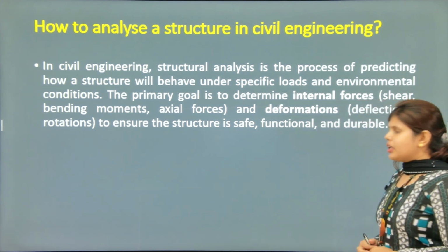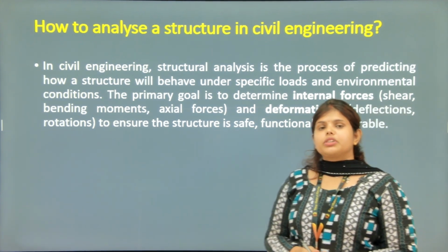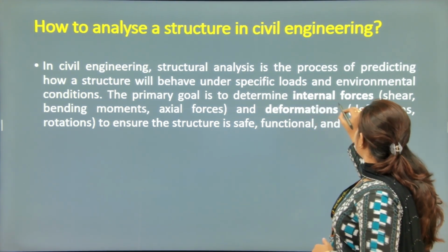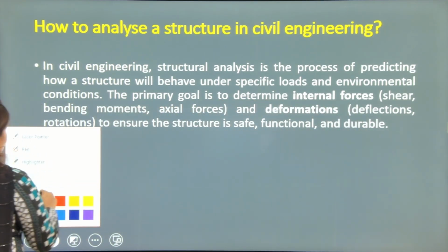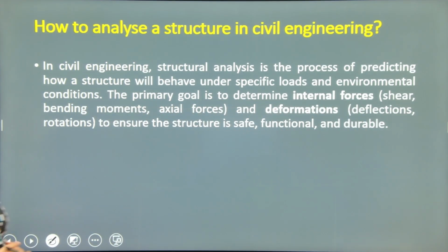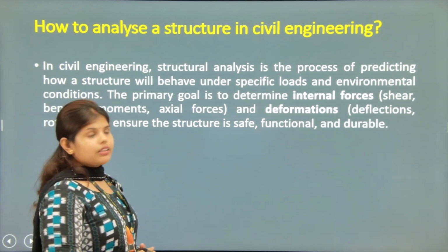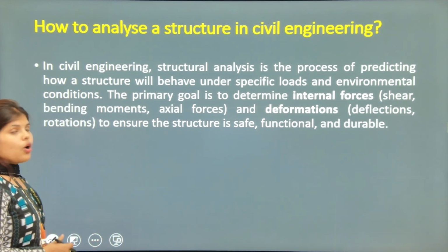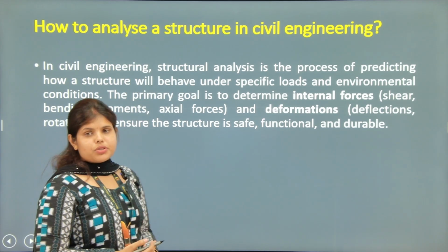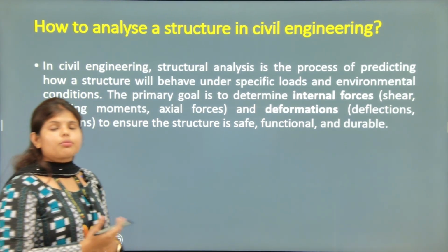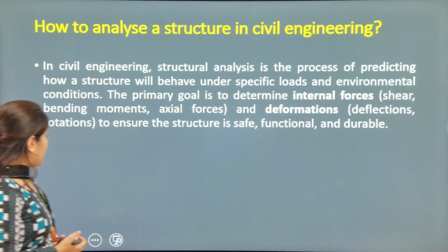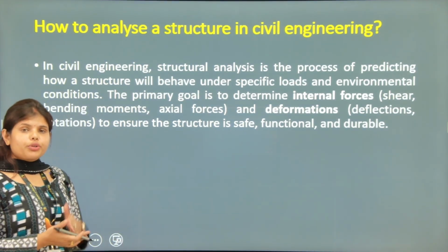So, the primary goal is to determine the internal forces, and from the internal forces we can find out shear, bending moment and axial forces, and also the deformation. From deformation we will get how much deflection of the structure is going to happen and what amount of rotation it will have.